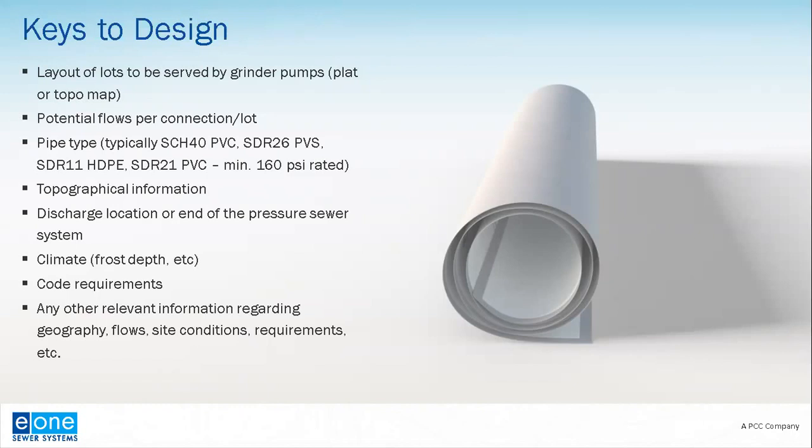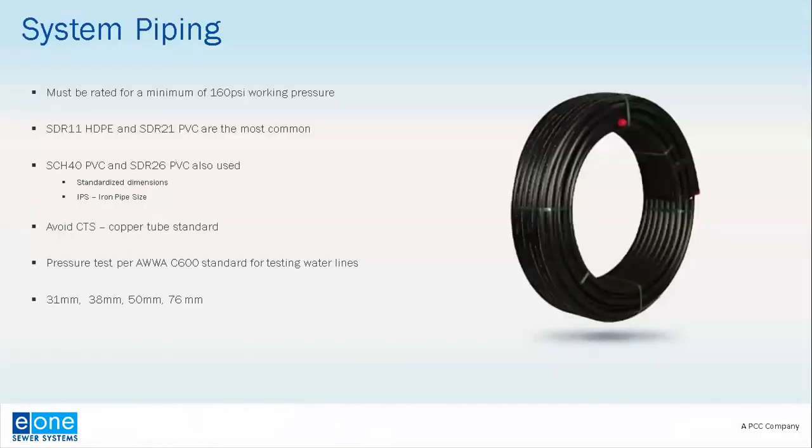Where is it located from a climate perspective? What is that minimum frost depth going to be? And what are the code requirements locally that might have to be taken into consideration? And also any other relevant information regarding geographies, flow, site conditions, or special requirements.